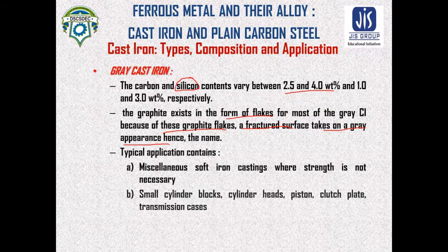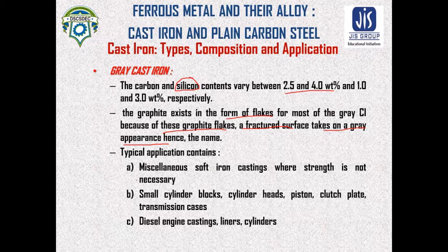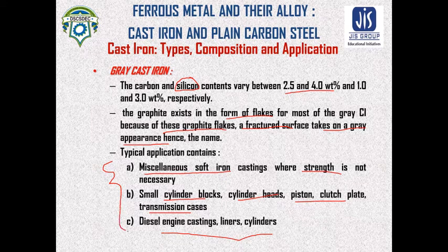So there are typical applications: miscellaneous soft iron castings where strength is not necessary, small cylindrical blocks, cylinder heads, pistons, clutch plates, transmission gears, and diesel engine casting liners and cylinders. These are the typical applications of grey cast iron.